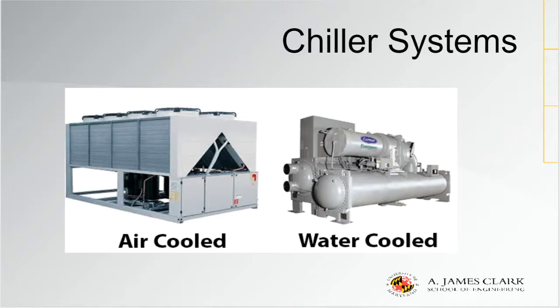Air-cooled chillers, on the other hand, use currents of ambient air from fans as a means of heat transfer. So they have no cooling towers, no water wastage, and lower maintenance costs. They're generally used in more specialized cases where environmental restrictions may exist. So it really depends on each and every situation which one you would want to use.